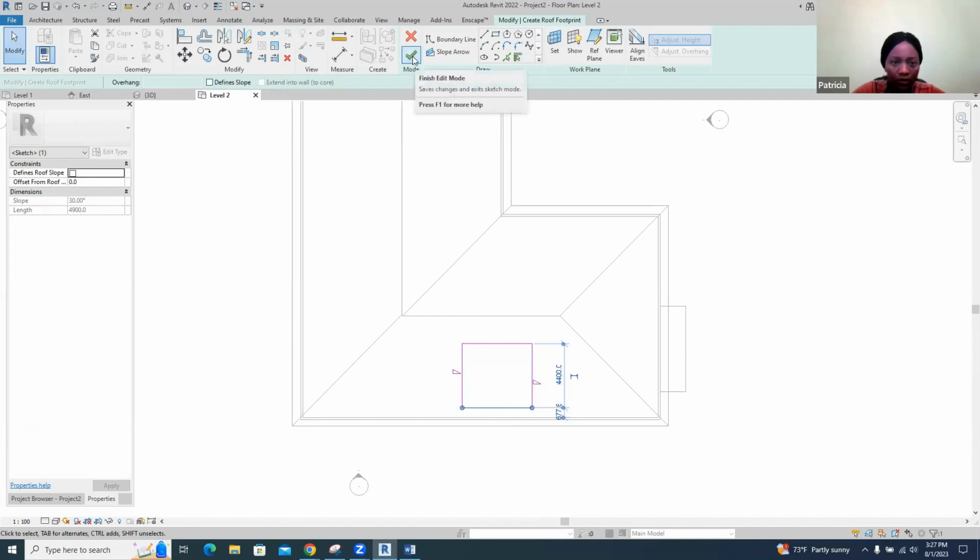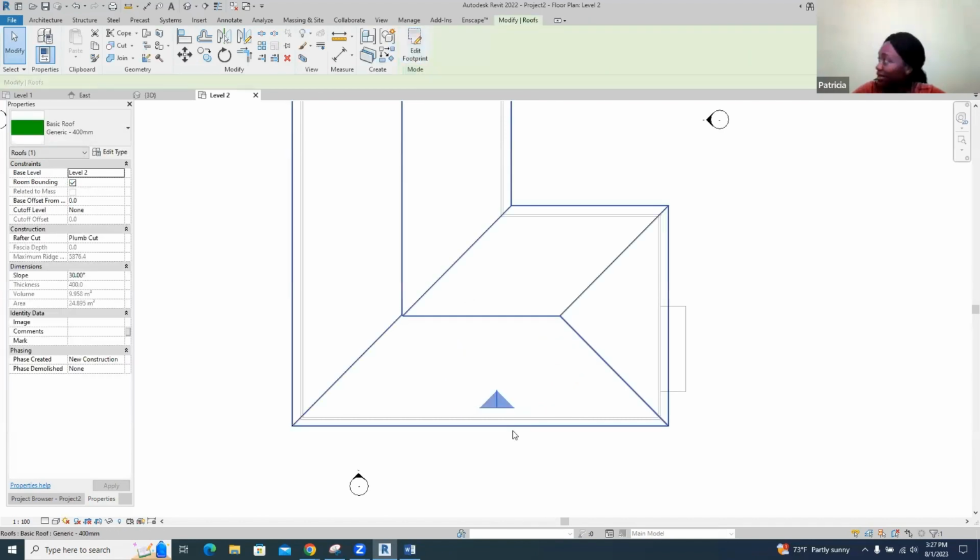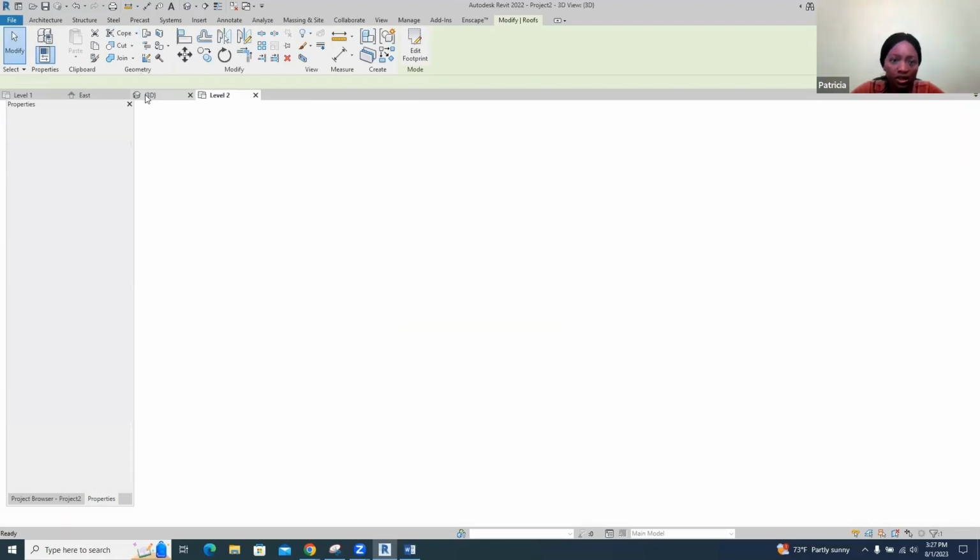So do we want to offset it from the roof? So when I check it, I see that it's buried inside the roof. So take the roof here, offset from the base, so let's say we're taking it higher by, I'll use the 2 meters, apply, so that's still, so let's make it 3, apply. So in the 3D view, let's see this roof that we made now.